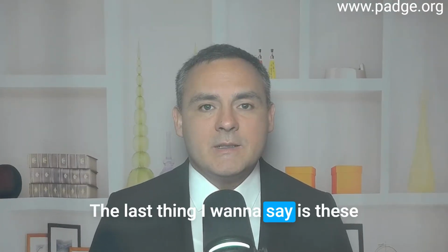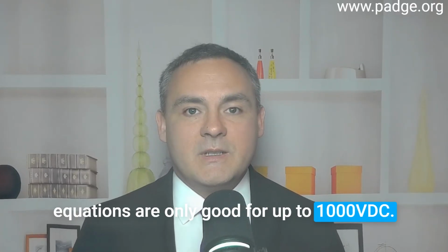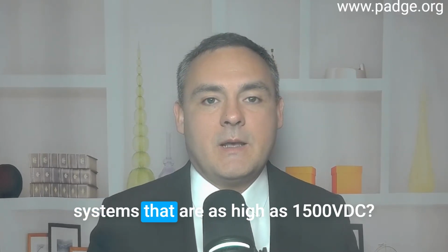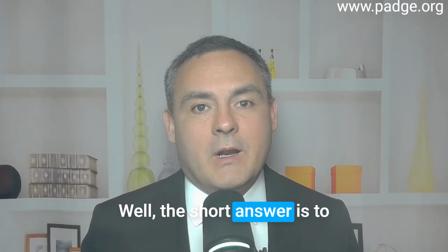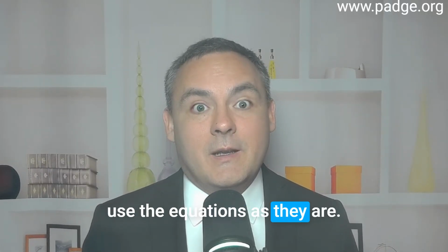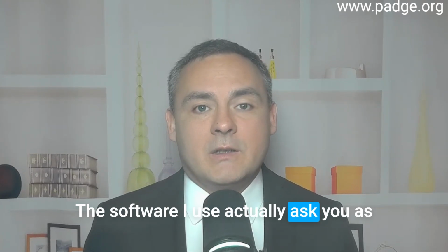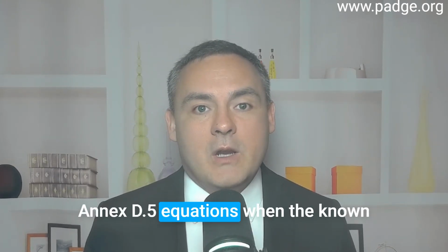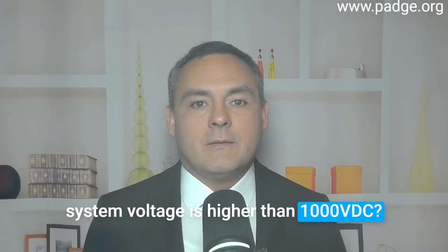The last thing I want to say is these equations are only good for up to 1000 volts DC. So, what do you do on these modern systems that are as high as 1500 volts? Well, the short answer is to use the equations as they are. The software I use actually asks you, as the user, whether you want to use the same Annex D5 equations when the known system voltage is higher than 1000 volts.